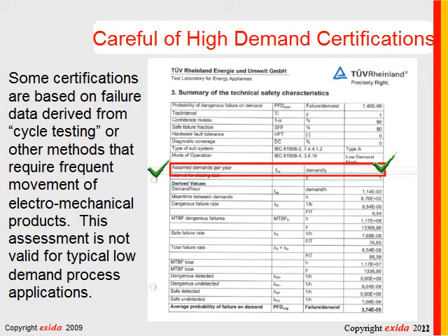So I would not go as low as 10. Our research shows you need more like 50 to 100. And that has a big difference when you scale the failure rate, as you might imagine, having the failure rate method described to you. But the bottom line is, don't just assume when there's a 61508 certified product that the failure rates given are useful and valid in low demand applications.